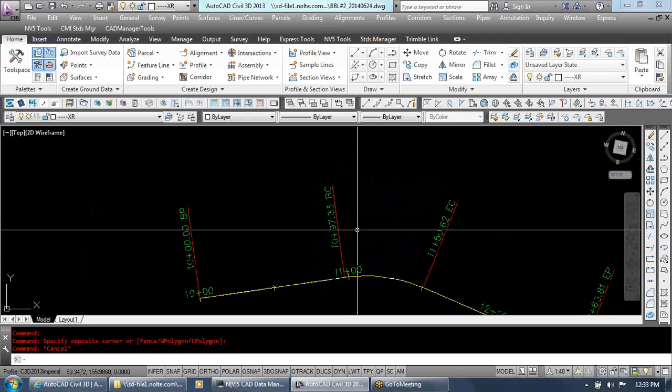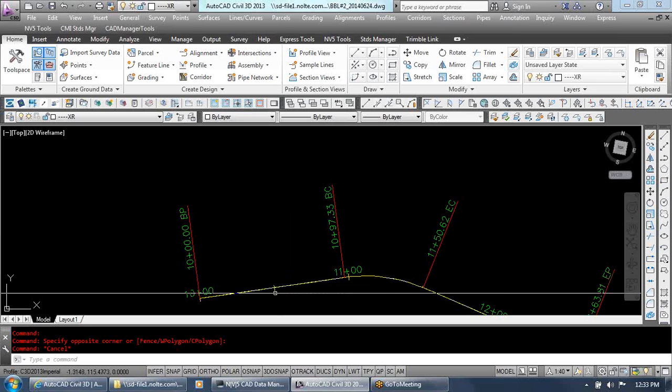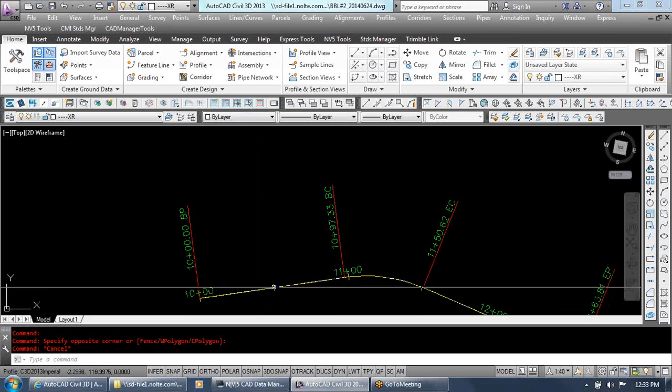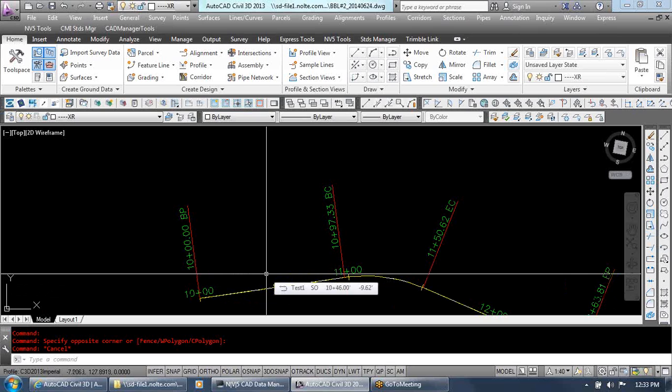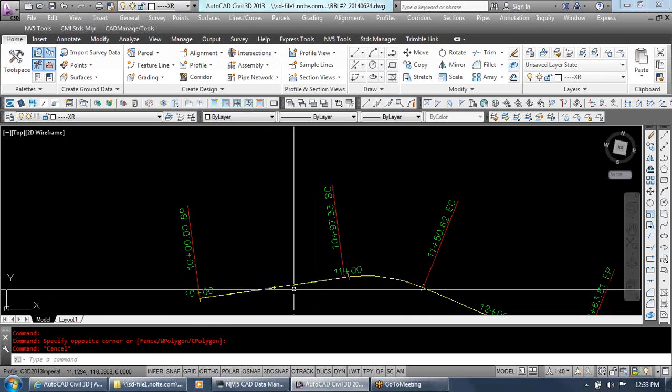The template that you guys are currently hopefully using, it's not on 0. They're all specified to a layer. And there's been some issues in particular on alignment styles. Sometimes the marker would come in and not be able to change color. Regardless of whatever you did, it would act like it's on 0 layer. So hopefully that's all been resolved with the way that these new styles have been developed.